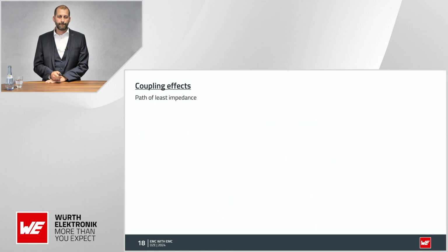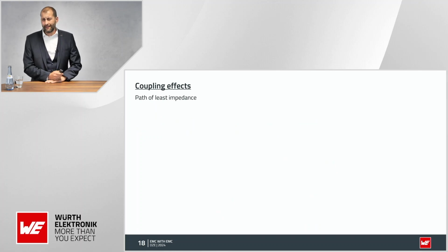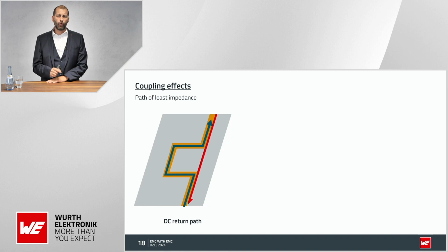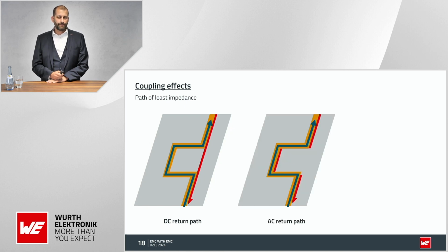It's a bit cryptic. And then if you go to the higher technical college in Austria, in the first year, you will learn one pretty simple rule. Current will always go the path of the least resistance. That's true, but only for DC current. As soon as you make things more complicated, and in this case introduce frequency into the equation, things change. In this case, the current will take the path of the least impedance.